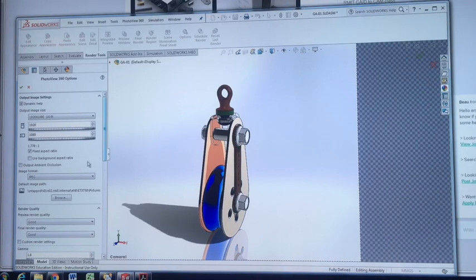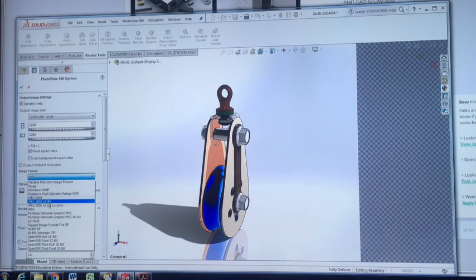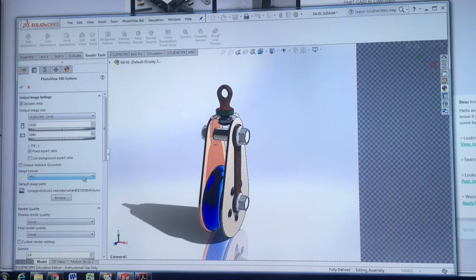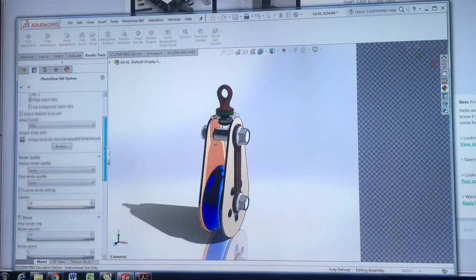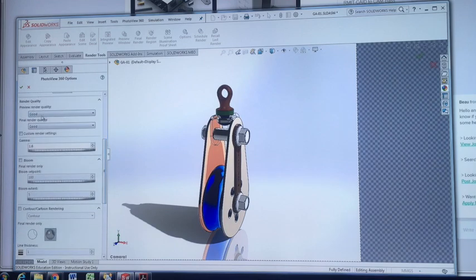You can set renders to automatically save files, in which case the image format here matters. All right, so there are all different types of images that you can save as. For learning, use JPEGs. Later on, use PNG files with transparency or TIFFs, but don't worry about that too much for now. Render quality, preview render quality. You can leave that at good. Previews are just for that, previews, okay? That's not the final render. You want that to be pretty quick.